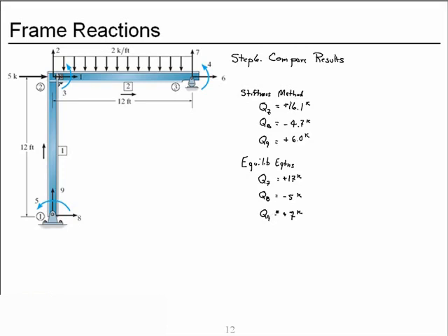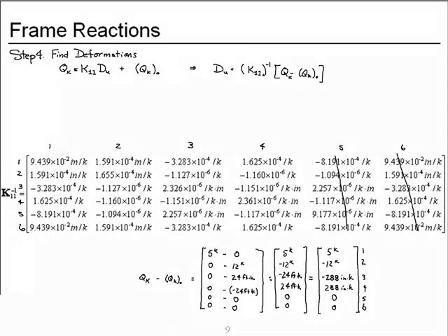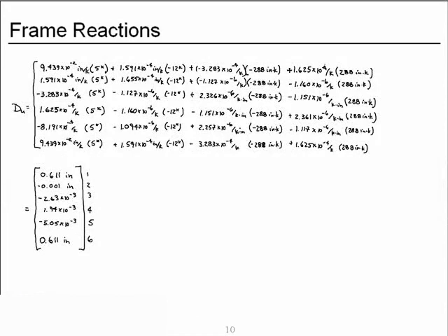So the question why should occur, and the answer comes from a quick review of the calculations we performed. We inverted the K11 matrix, which introduces round-off error. Our calculations of the deformations involved adding and subtracting large numbers and trying to keep the remainder. That's called subtractive cancellation, and it introduces even more round-off error.